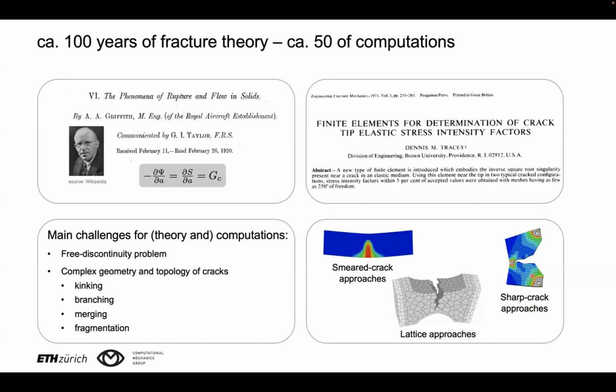Cohesive zone models are very efficient if you know upfront where the crack is, which, however, is not always the case, is actually rarely the case. And the XFEM and GFEM, they are giving good results in 2D, but their implementation becomes extremely cumbersome and extremely complex in 3D. And lattice approaches also have their own drawbacks.